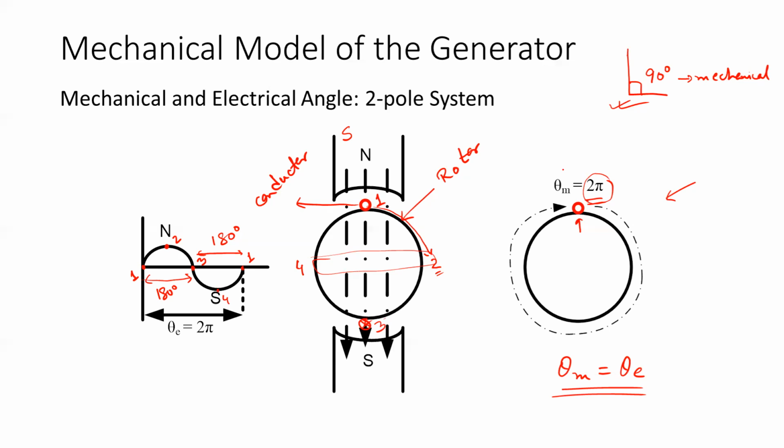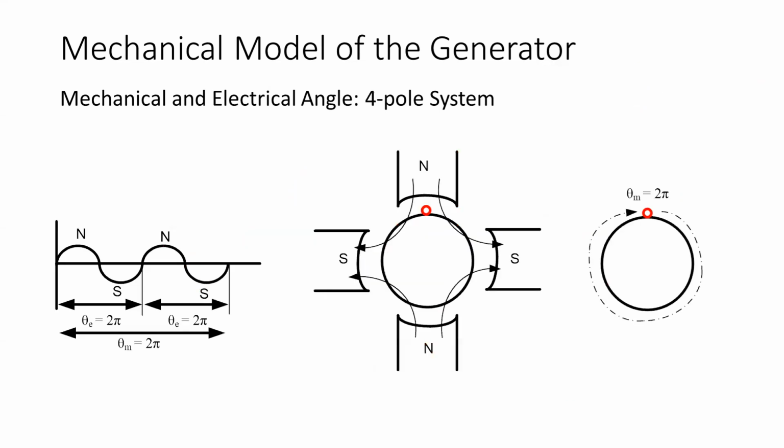But when we come to our electrical angle, it is related to the number of poles, how many times we cross north, south, north, south. That is what dictates my electrical angle. Is my last statement clear? Yes, sir. Fine. So now let us see what will happen for a 4-pole system. Of course, it's written already over here, everything. The graph should have been hidden in the first case.